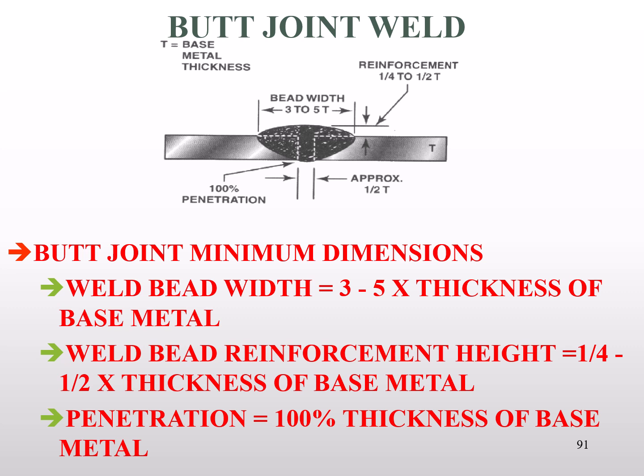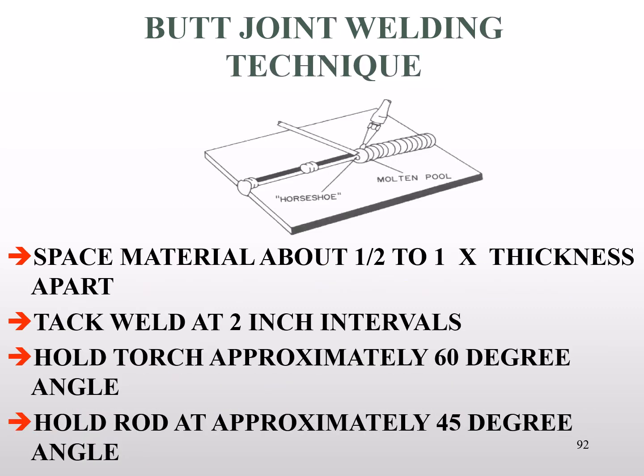Should be 100% penetration. And the way you get that is by establishing a gap between those two parts and melting the filler all the way down to the bottom between those parts, then build back to the top side slightly above surface level. That's the way a good joint's made, and that's the way to answer that FAA question.